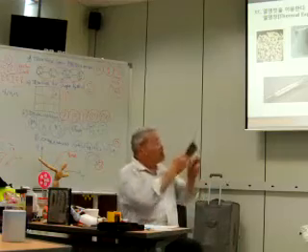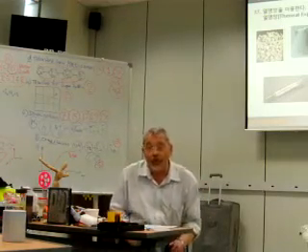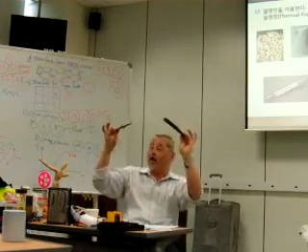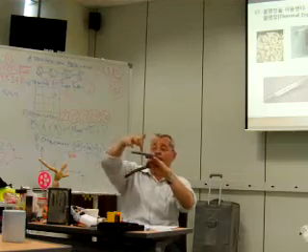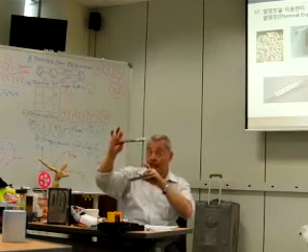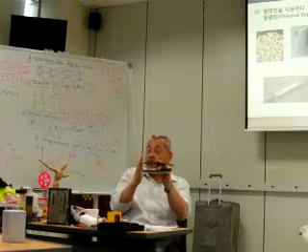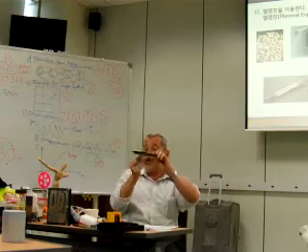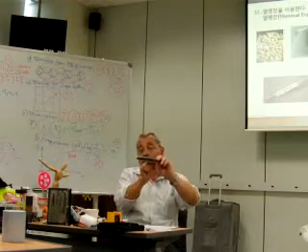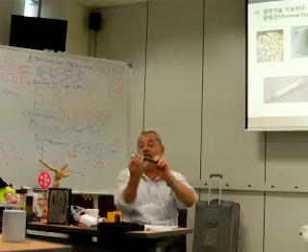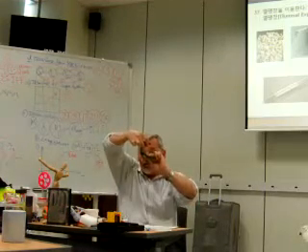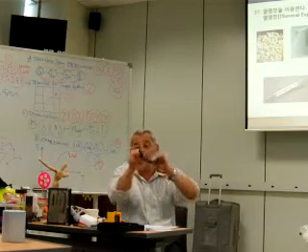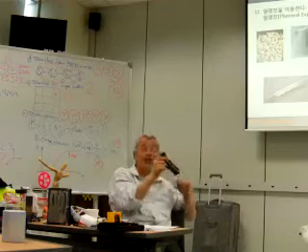And thermal expansion you can found in your apartment because you have kettle with sensor about temperature. This sensor have two parts. It is bimetallic flat. For example, one flat from copper, other flat from aluminium. Copper and aluminium have different coefficient thermal expansion, and if you create combination and increase temperature, one will be increased more fast, and you will obtain bending of bimetallic flat. And it is thermal sensor. It is principle of operation for thermal sensor, and you see it in picture.